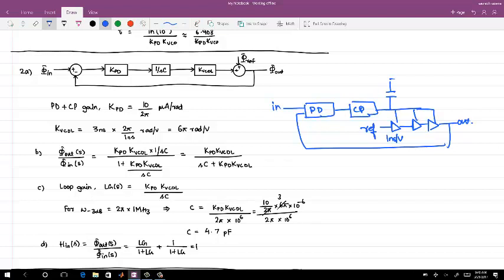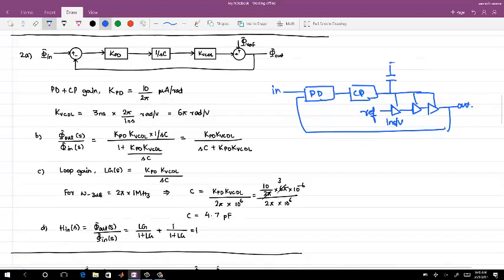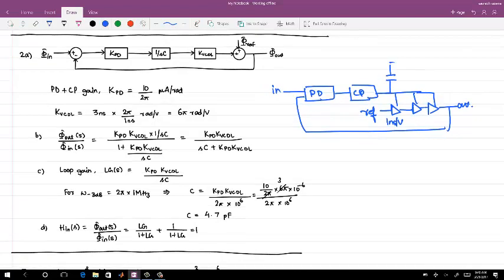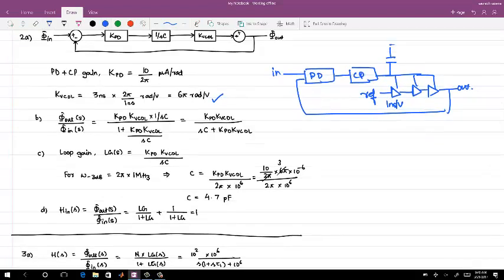Did you get confused with any time here with the KVCO thing or something? No, right? It's directly the delay. So you have 3 nanoseconds delay, and from the delay you can convert the gain into the phase factor, right? So this one is converting the voltage to the phase using how much delay you have. Okay, phi out by phi in is again the same simple transfer function.